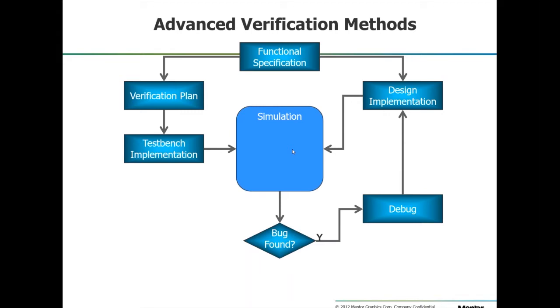Then you want to start testing failure cases. So you send a bad packet, you corrupt a bit of data, and then the correct response from your device is that the CRC doesn't match up with what was transmitted. You've got to resend that packet. So that's fairly easy.